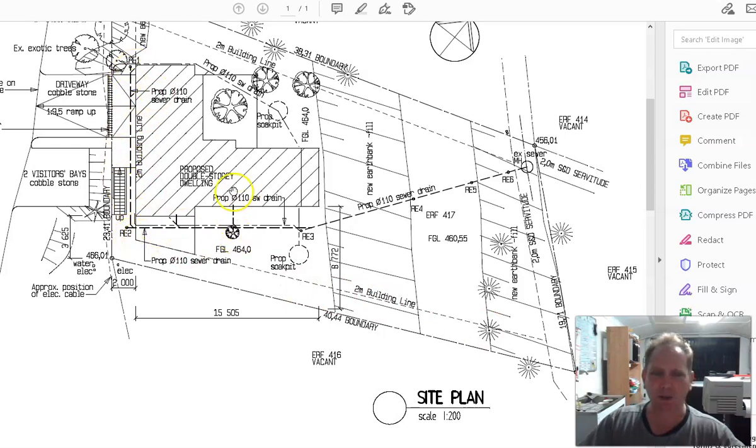Here's your sewer lines. You can see your sewer lines going all the way to a manhole and then off your property. That manhole should, somewhere you should have a cover level and invert level for that manhole. You should have a sewer section somewhere on your property, on your page, sorry. Okay, ramps. There's a ramp, parking bays.